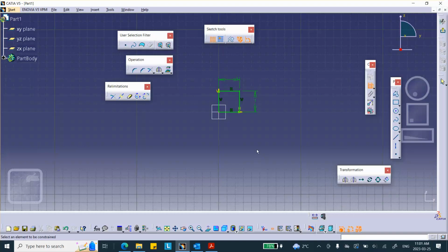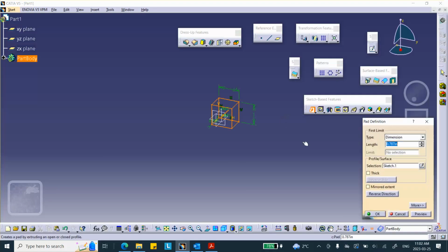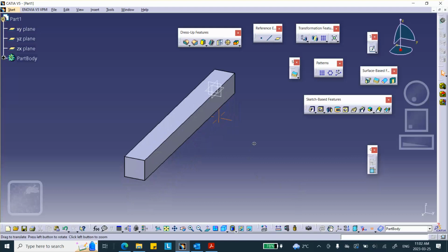Incidentally, I'm doing this thing with solid elements. A more appropriate element to use is beam element, which I will not do in this particular tutorial. I have done it in the class as part of my activities. I've shown it to you, but will not do it in this particular video. Okay, so exit, and then we pad it by 10 inches. So there is my structure.